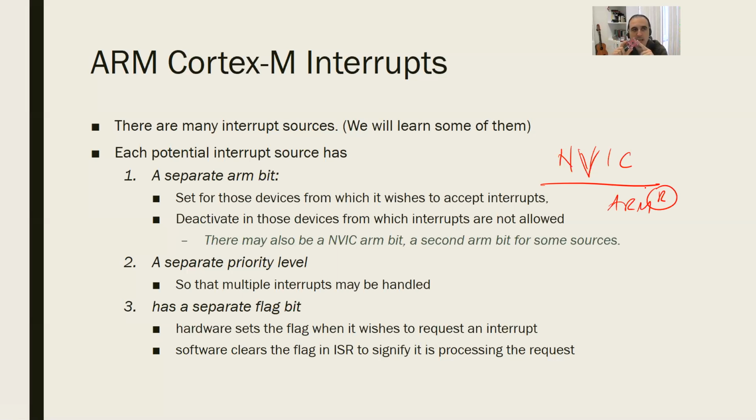This one has an analog to digital converter. So when you connect an analog sensor and you are trying to digitize it, you can create certain interrupts. If the digital value rises above a certain value, you create an interrupt. This way you can create very nice sound systems with this card. I've seen very nice MP3 players and vocal effect devices with this card. It's very capable. It's actually a signal processing card.